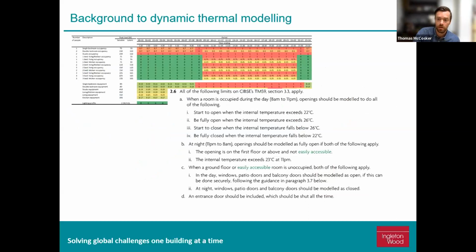The TM59 methodology is a prescriptive methodology, which means that it has certain gains you must account for within each occupied space. The gains and their allowances have all been based on the DECC's Household Electrical Survey. A TM59 model must use these gains and the profiles associated to illustrate how the building is likely to perform under the tested weather conditions. Part O has adopted this TM59 methodology largely in its entirety. There are some minor amendments which are mostly just this window opening augmentation.